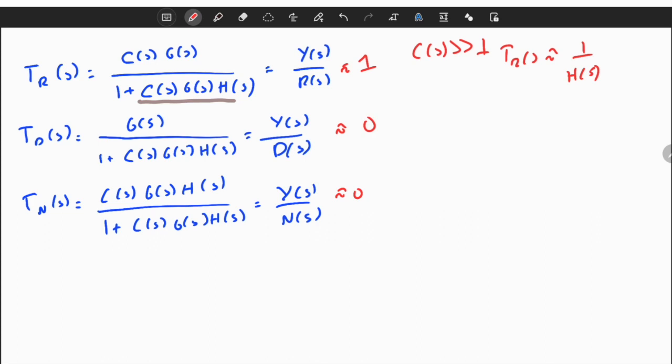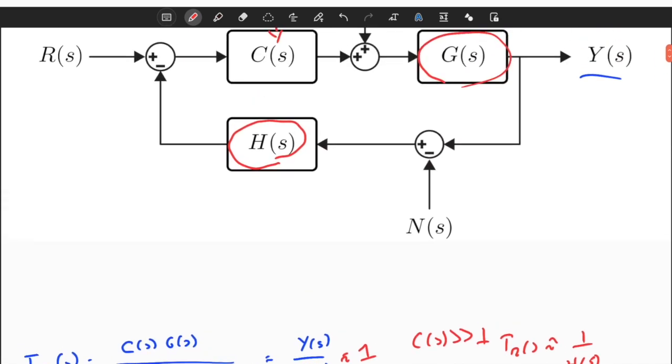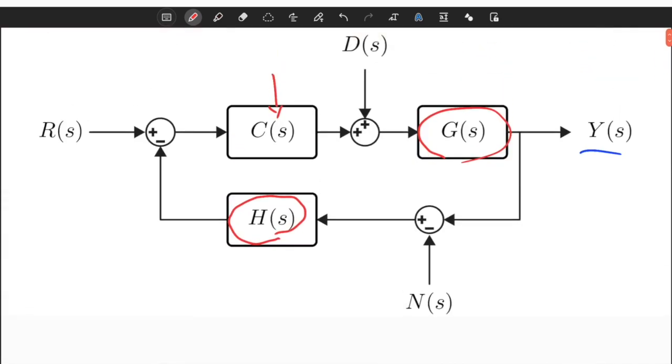So what is H? It is the transducer dynamics. So it says that there's a limitation. We can make a perfect controller, but we are somewhat limited by H, which is true. First of all, it means that there shouldn't be any DC bias between Y and R. If H of S is equal to, like, 1 or 2, it means that you're technically measuring the output wrong. It also says that there shouldn't be a big phase lag in H of S, which also makes sense, because it would mean that you are measuring something that is in the past, which is kind of wrong.